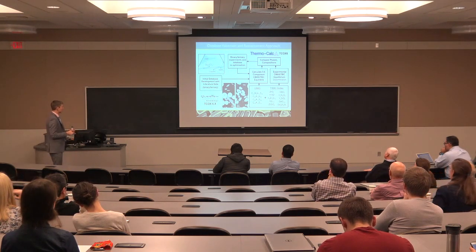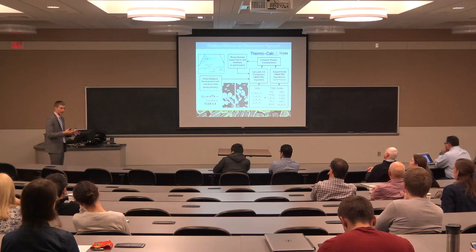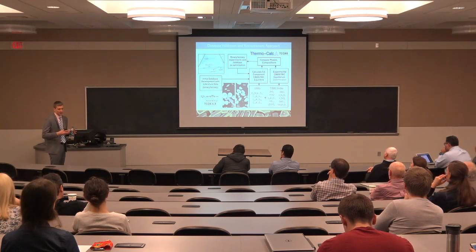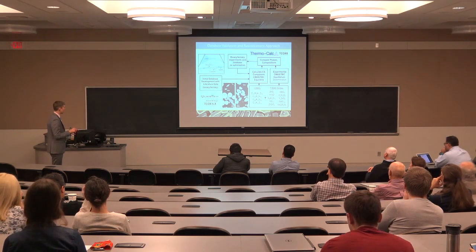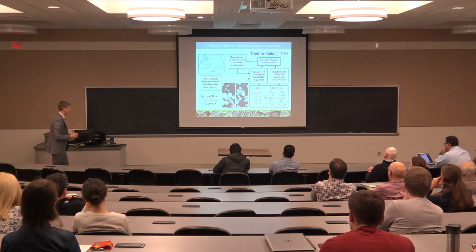The general approach to build one of these databases or expand one of the databases is to do the initial development with an understanding of what the phase equilibria in the systems are. But you can't get that complete understanding of a 6-component system. And so the initial development is based on binary and ternary systems, and then you extrapolate to the higher order systems.